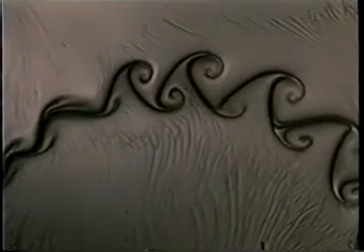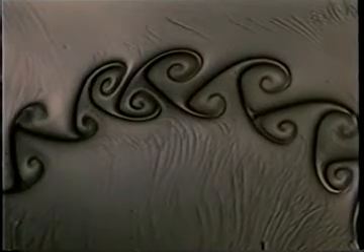Increasing the Reynolds number by increasing the velocity, the flow around the cylinder becomes unsteady. A vortex wake develops, the Kármán vortex street. Just below critical Reynolds number, the stability is precarious. A small accidental disturbance is enough to trigger large fluctuations.